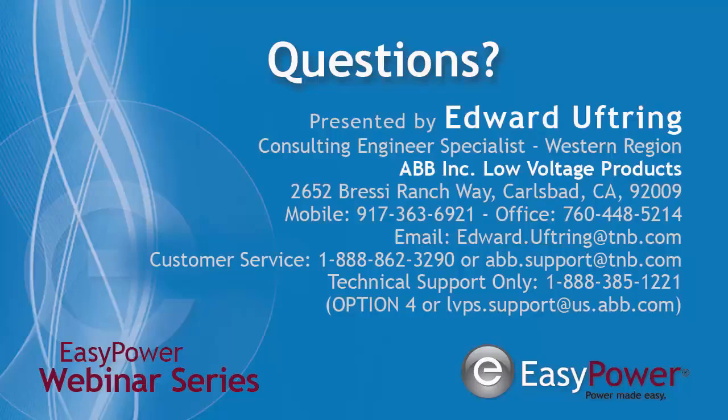If the circuit breaker is several years old, let's say 40 years, is the interrupting capability kept constant, or how can it be rated by the years? So that's a great question. Generally, there are a lot of these old breakers out there. You can't really tell based on the years because, depending on whether you're using a service that's really lower than its rating, you can go for 40 years and not have a problem. If you're never interrupting or never having any fault issues, those contacts aren't wearing, it can go forever. Typically, we would recommend changing it out after about 10 to 15 years.